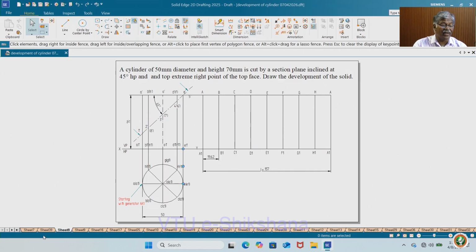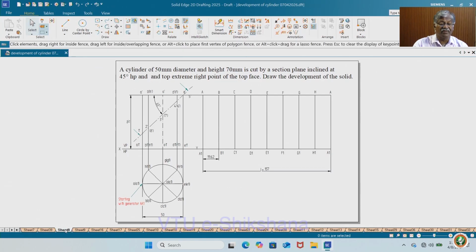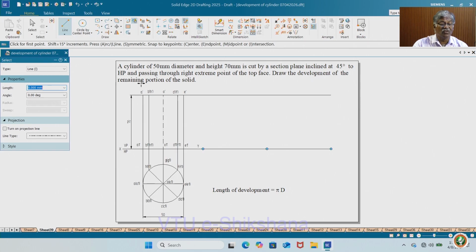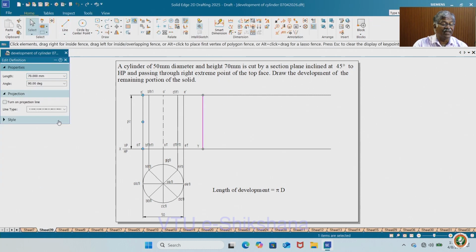Now to get this pattern, now I will show you. There are two methods. One is the offset method, other one is rectangular pattern. Now I will tell you both. Now first let me use offset method. For that you have to draw a line. First you have to start with a line, that is, assume that one particular generator, you can start from EA1 or EE1, all depends on the situation. Otherwise also you can start from E1. I will tell you in future how to do it. Now let me have a thin line. First this represents the particular generator EA1, say.